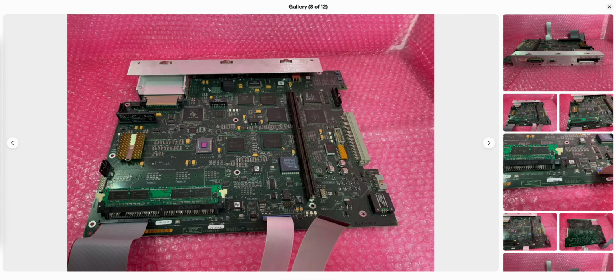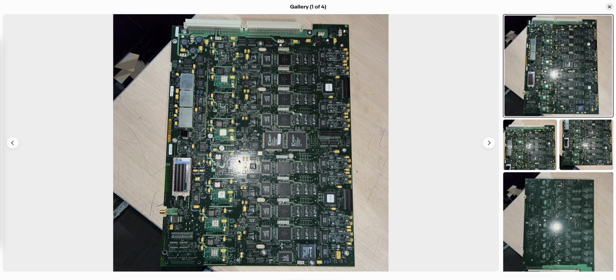So the core of the oscilloscope is this computer basically. This is a full computer on a board powered by PowerPC. Through this slot, it communicates with the Intel PC on top of it, running Microsoft Windows. And through this bus it talks to the acquisition board. Those devices have an impressive acquisition board with a lot of FPGAs. That's the part that is talking with those slots where the sampling heads reside.